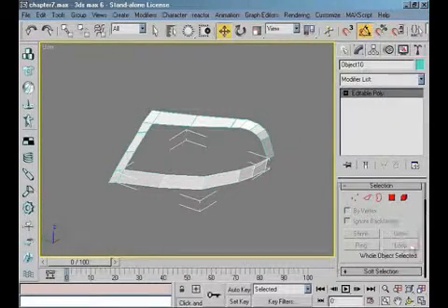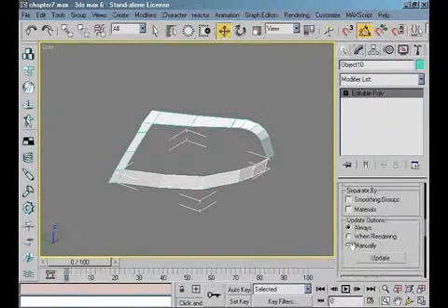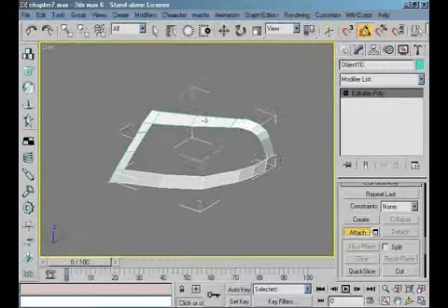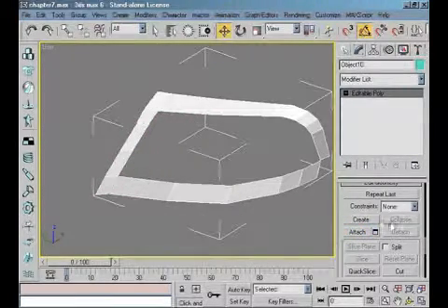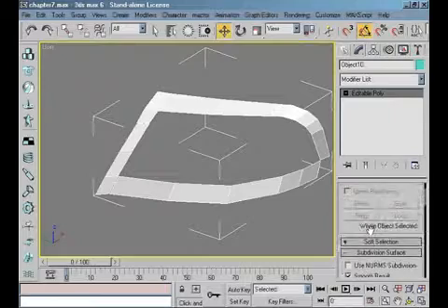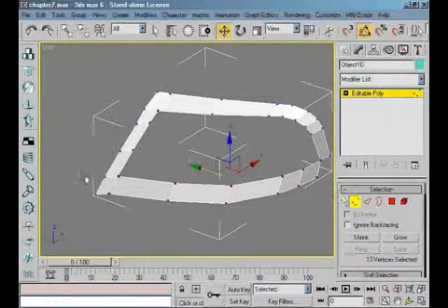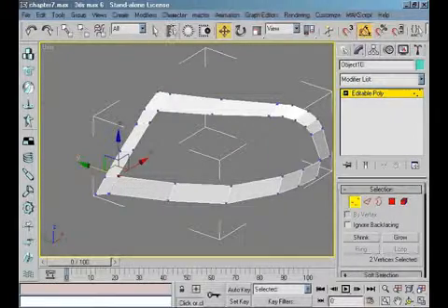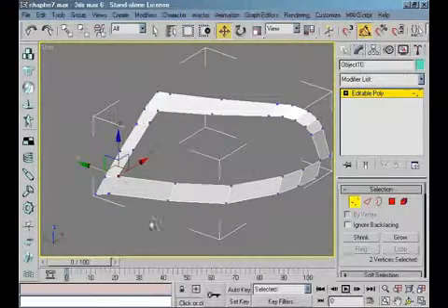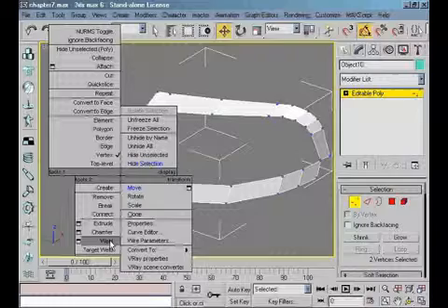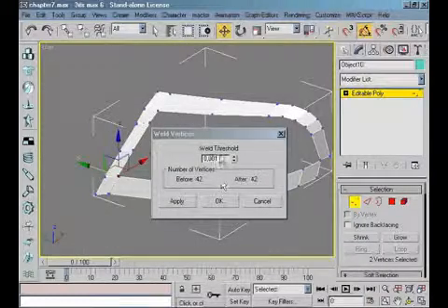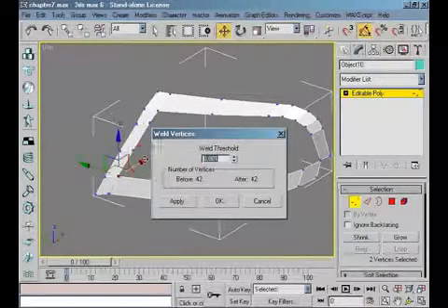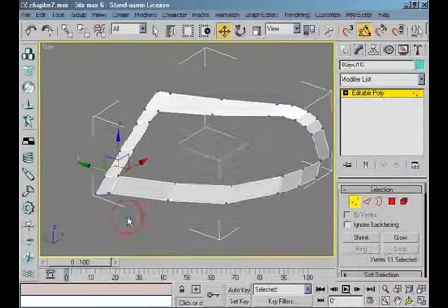Okay, the outlines are finished, so now I have to attach them and then weld the vertexes to reduce small holes. As you probably remember, we had to do the same when we were doing the window seals, but with this small difference: here you will rebuild the whole surface between outlines. Well, I can give you a little tip. When you model the hood and front bumper, try to keep an equal number of segments on both models. This will help you a lot when creating lights or the grille.